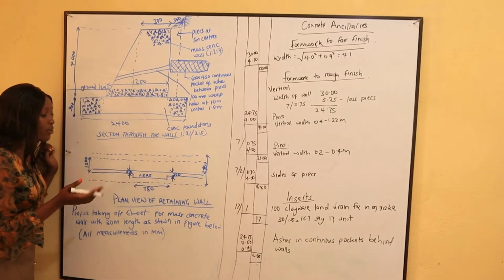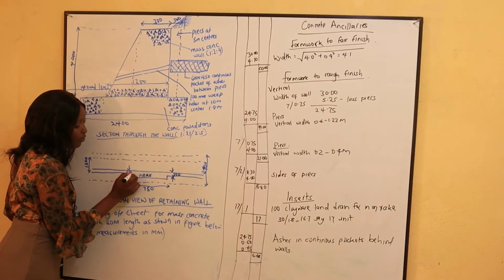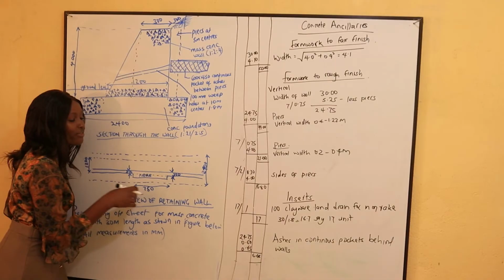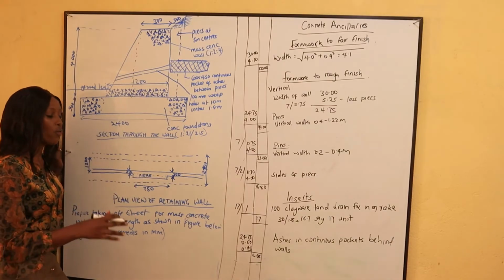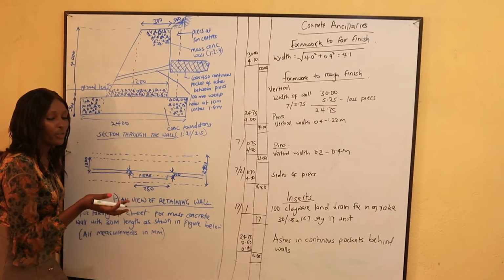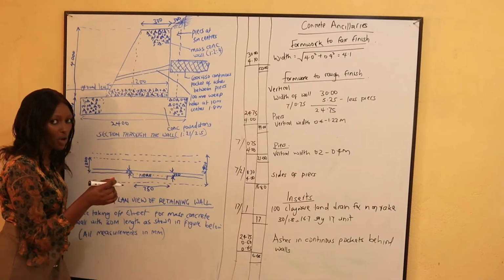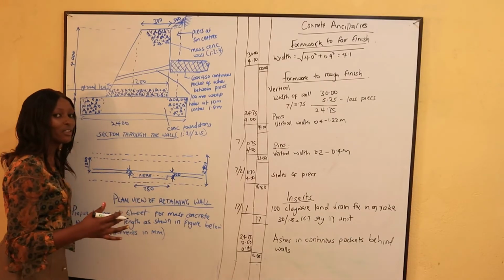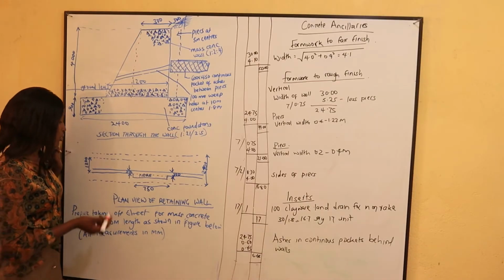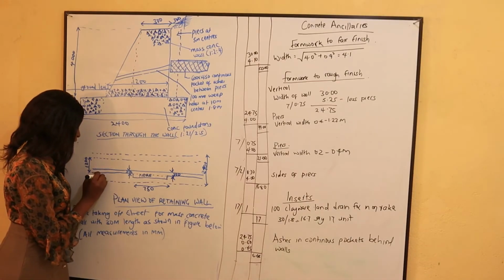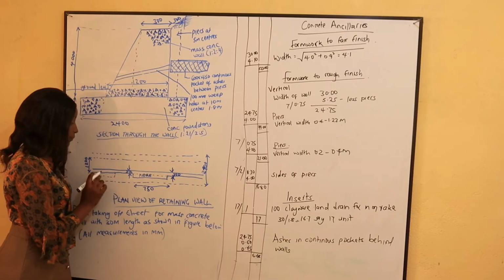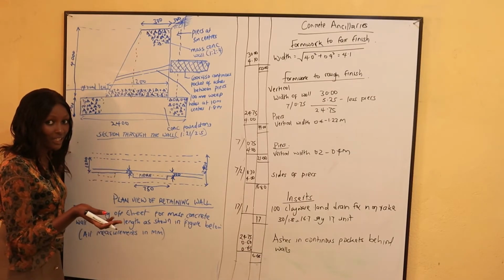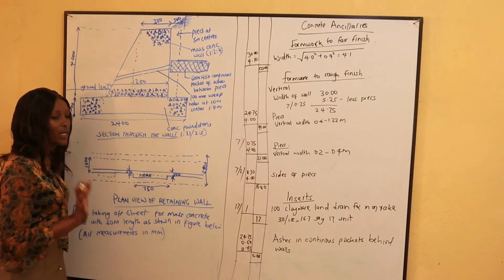You know, we don't need to support formwork for the wall which is behind the pier, because we shall first do the piers, then we shall do the wall. So the piers shall support the concrete that shall be done on the wall. Alright, so behind every pier, we don't need to calculate the formwork for the wall. And you remember, these piers are in intervals. So whenever we have a pier, we shall deduct that length, because we need the length for the wall alone.